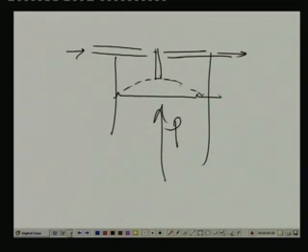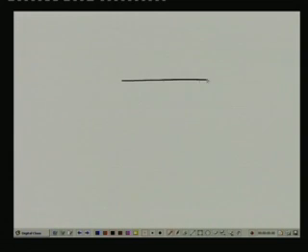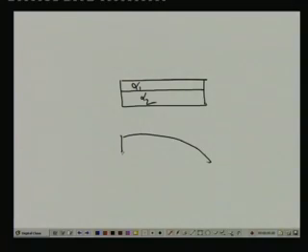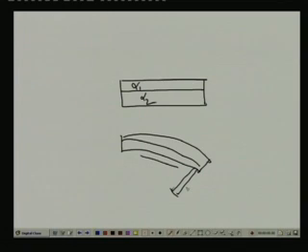Also, in the case of the bimetallic strip, which is used for the measurement of temperature, and also can be used for switching, if the temperature increases, because of the two different coefficients of expansion, alpha 1 and alpha 2, it bends like this one, right. So, now if this tip is connected to a shutter, obviously you will find that the light will be modulated, right. So, this is one other way of doing that thing.